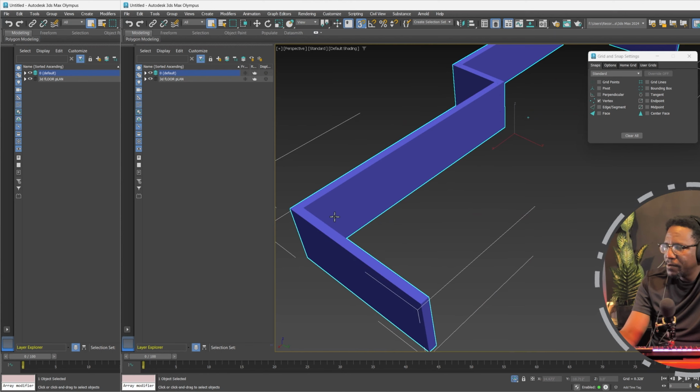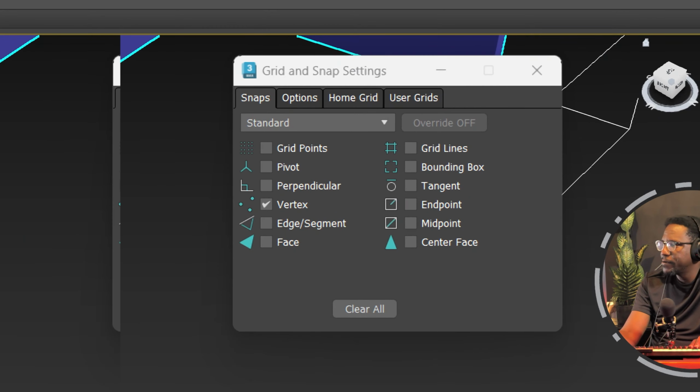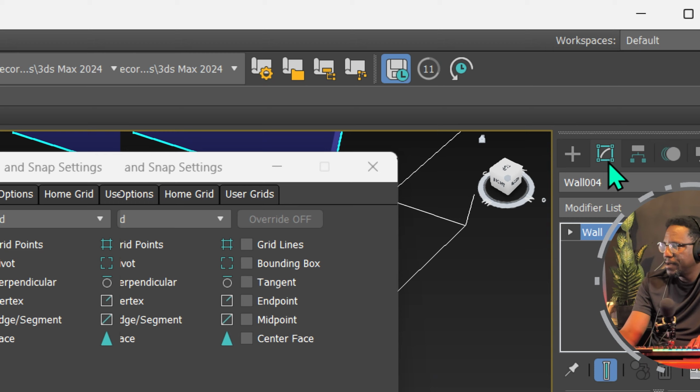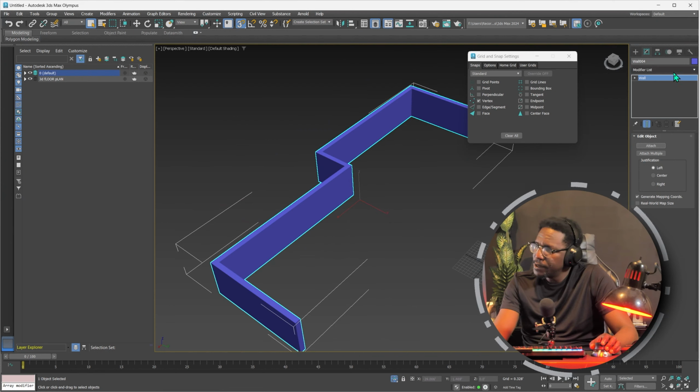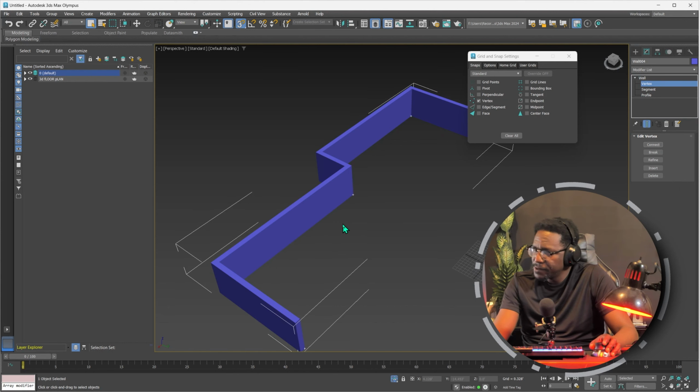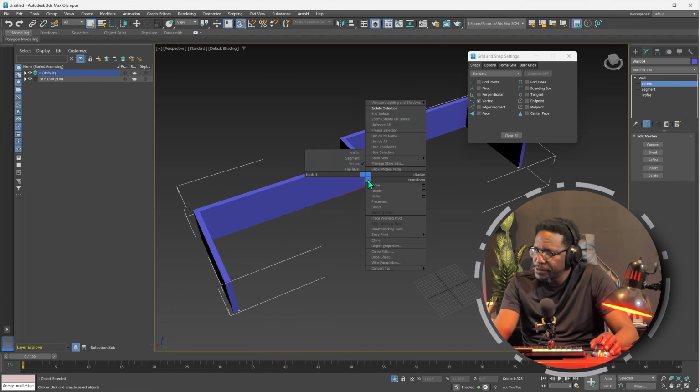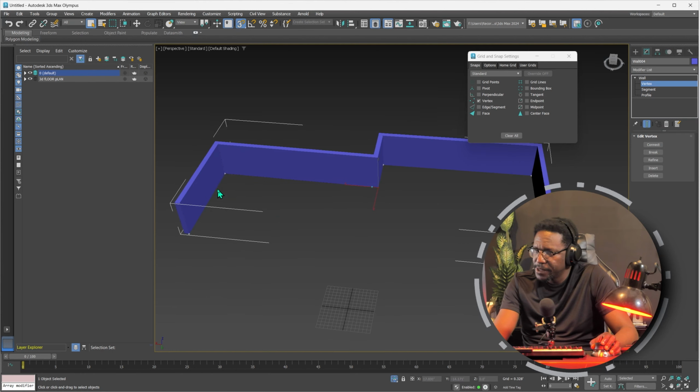All right, so we're going to click on the wall here. And remember before how we went to create, and these were things we could create. Well, now we're going to head to the modify tab, which is here, right? And well, what do we want to modify? When you select the wall, you see the modify tab says wall. So then what we want to do is expand this down and choose vertex. And that now allows us to be able to select the vertices that make up the corners of the walls.